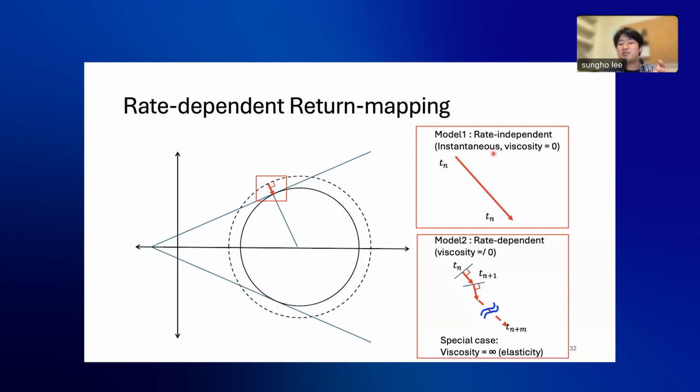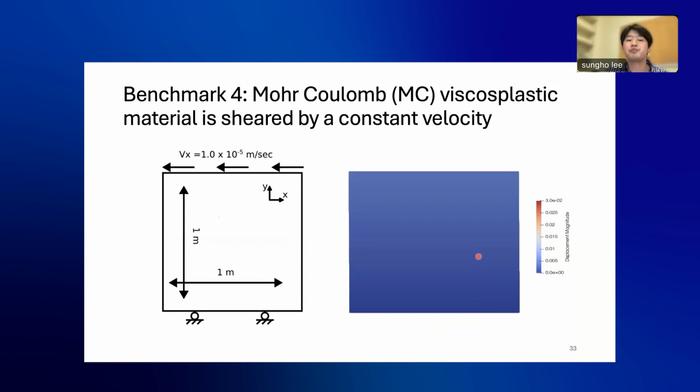The rate-independent model, this type of model is known to be highly sensitive to numerical mesh size. So if the mesh becomes smaller, the shear band shrinks. But Lagrangian is involved with the mesh change, so the shear band goes to 0. So it is kind of a numerical mesh issue. To resolve the issue, the rate-dependent model is suggested. And that's why I implemented this feature, the model.